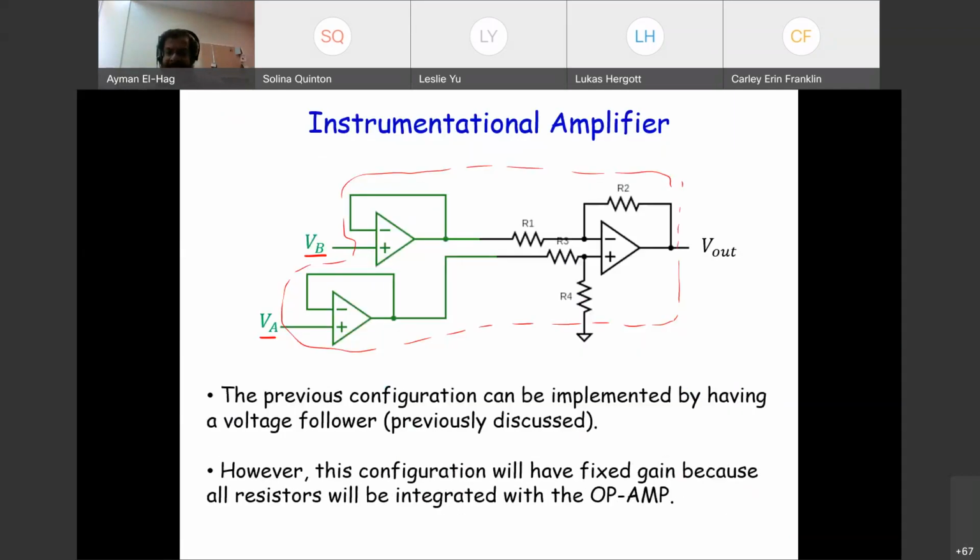Now, still here we have one small problem. I just mentioned it a little bit when I talked about this amplifier. We said that R2 over R1 is equal to R4 over R3. So they are the same ratio. It could be the same values, specifically R2 and R1, R4 and R3, or the ratio could be different. This could be, for example, 10 and 2, and this is 20 and 4. Same, you will get the same thing.